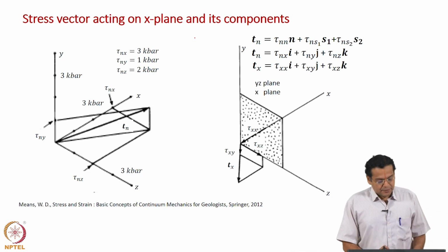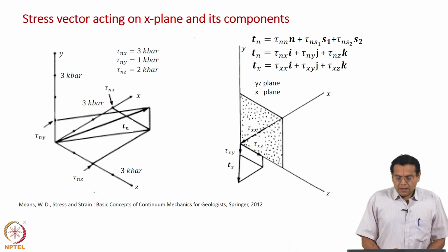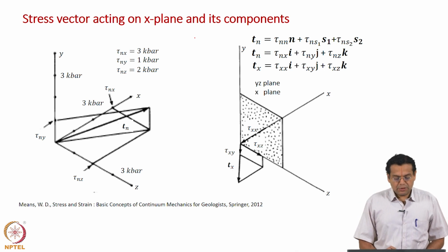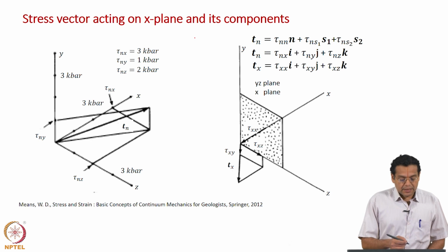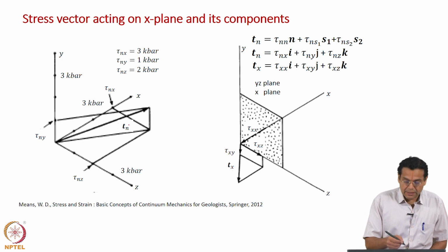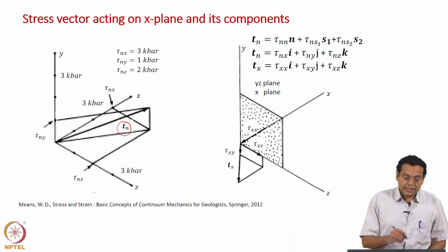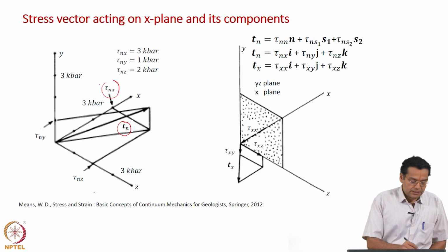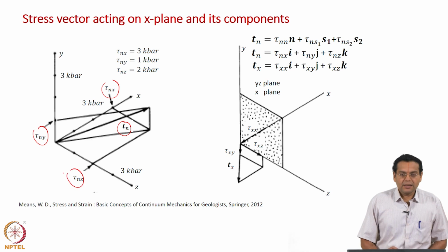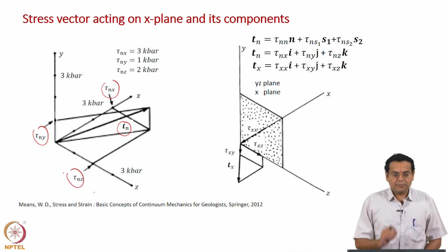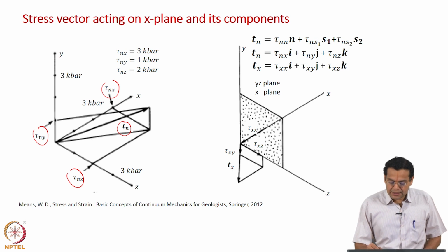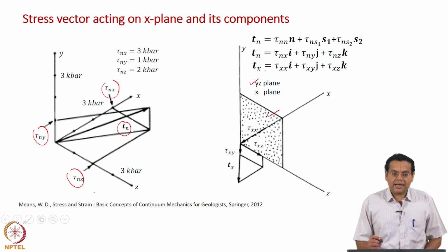Now, what is shown here: in the slide prior to that, we resolved the stress vector on any plane along the x axis, y axis, z axis. Now instead of any plane, I have a well defined plane. As I told you, this is the plane which you call the x plane, or actually the plane is in the plane of the y z axis.